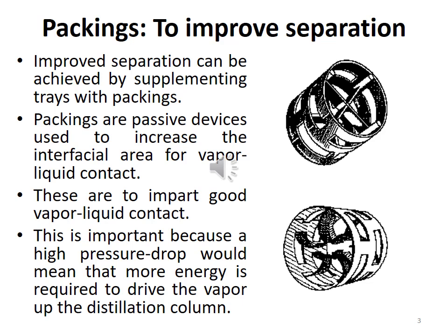They are designed in such a way that they will increase the interfacial area of the vapor liquid contact. It means these packing materials will offer a higher interaction between the vapors and the liquid. More chances of interaction between the vapors and liquid will offer a better separation efficiency. In this slide you can see some pictures of packing material. These are supposed to impart a good vapor liquid interaction.